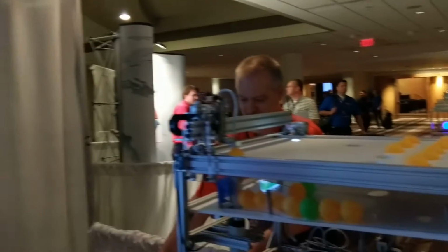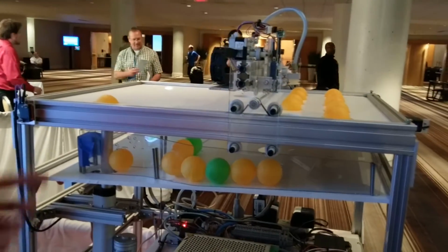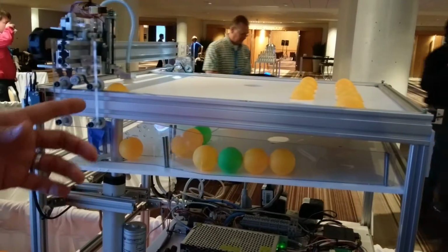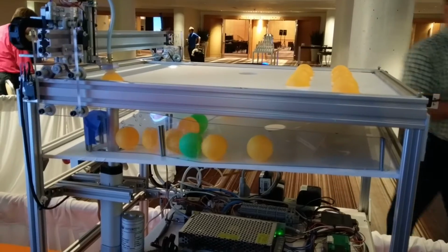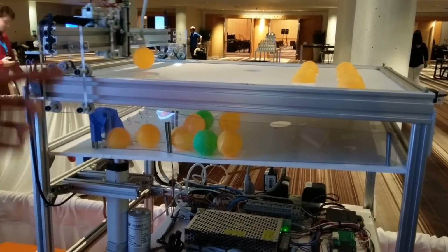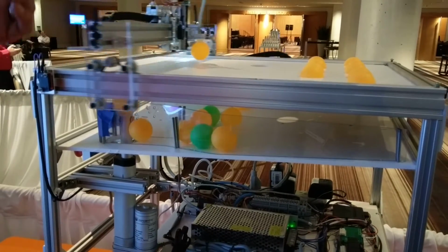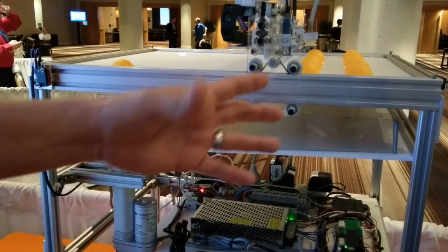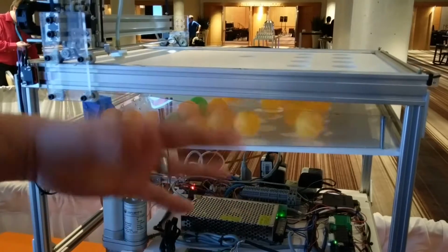Right, and what do we got going on here with the ping pong balls? So here we've created a machine to represent a shop floor manufacturing system. It starts with feeding in a ping pong ball. Oranges are considered good in production, greens are considered bad and scrap. So it's taking that ball over to the color sensor, it's checking it's orange, it's good. Hey, we filled the standard pack quantity, so it's now going to dump those.